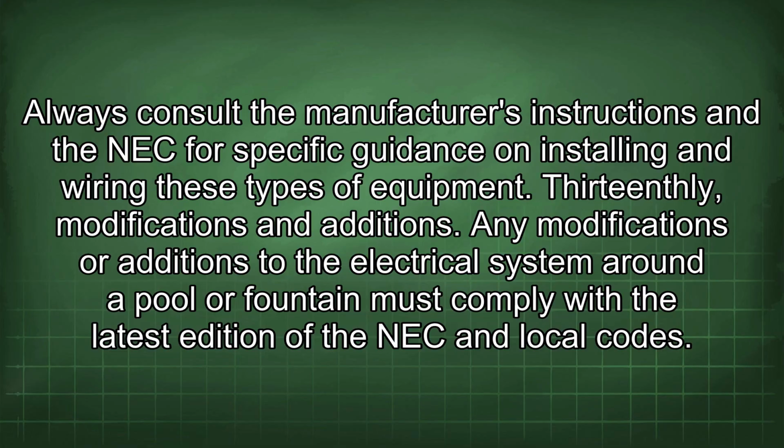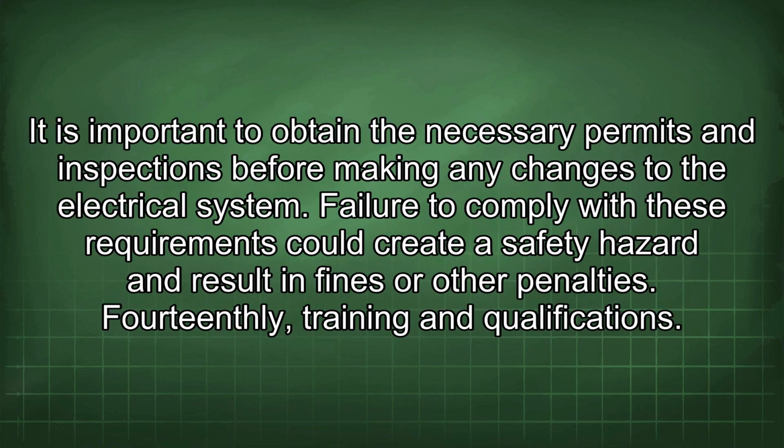13thly, modifications and additions. Any modifications or additions to the electrical system around a pool or fountain must comply with the latest edition of the NEC and local codes. It is important to obtain the necessary permits and inspections before making any changes to the electrical system. Failure to comply with these requirements could create a safety hazard and result in fines or other penalties.